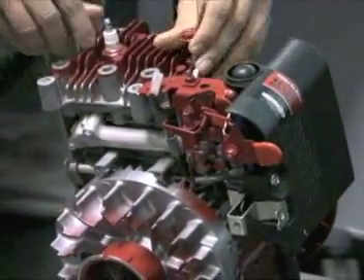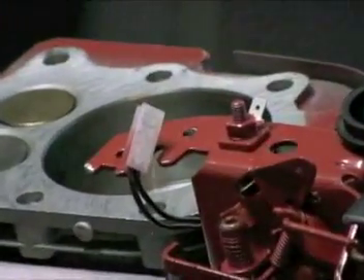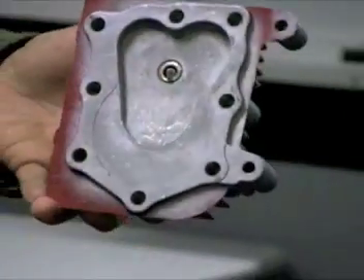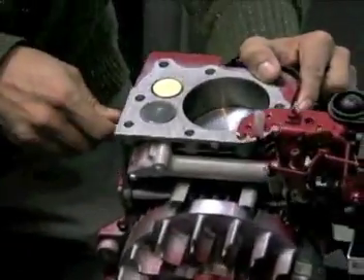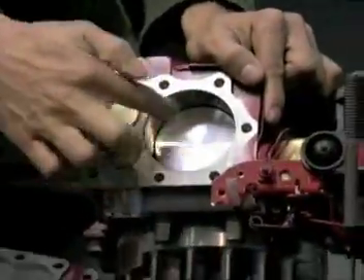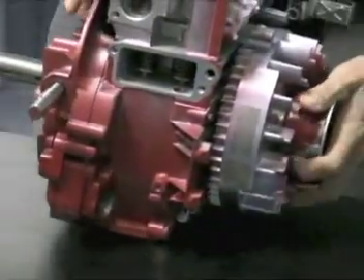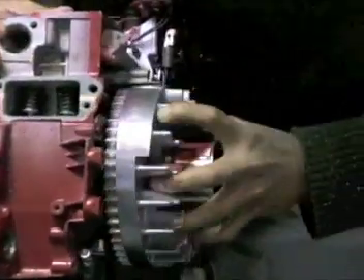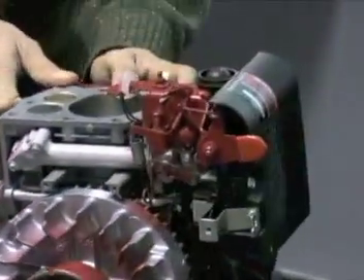If I take off the top part of it and show you, this is where the clearance volume is right here, and there's the spark igniter right here, and this is the electrical connection that goes in from your battery. You can see the two valves, one is the intake and one is the exhaust, and we have the cylinder and the piston. The valves are connected through a camshaft, with a spring device connected to the crankshaft, which helps operate the valves at the right time.